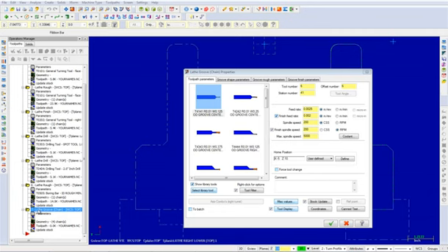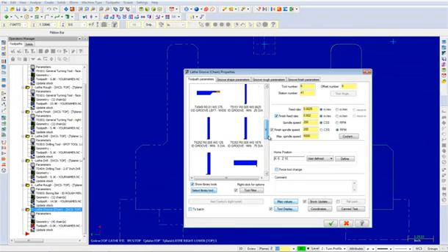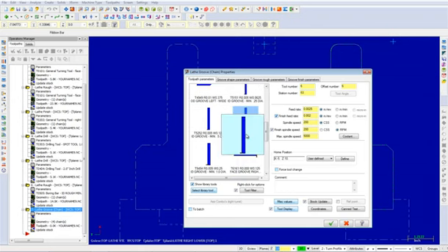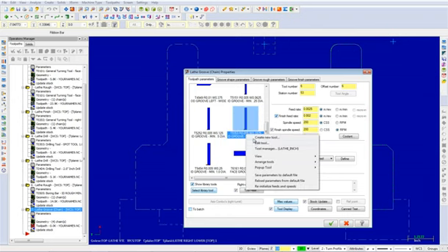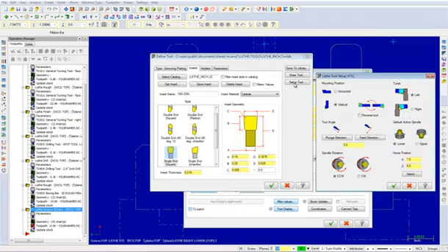From the tool list, select the ID Groove Min 0.75 diameter tool. Right-click on the tool and choose the option Edit Tool. From here, pick the Setup Tool button and change the turret to right side. Select the OK button to exit the Lathe Tool Setup dialog box.